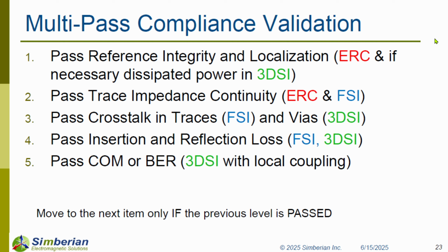If this step passed, and it can be done in ERC, again with Simbeor Verify license, more accurate analysis of losses on vias can be done with SerDes SI, and specifically with SerDTF or SerDML solver, where you can evaluate the dissipated power on each via. See more on this in the recent DesignCon paper with Alex Manukovsky and his team from Intel on via design up to 100 and 120 gigahertz actually, and how the localization is evaluated.